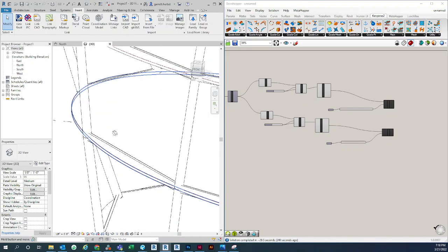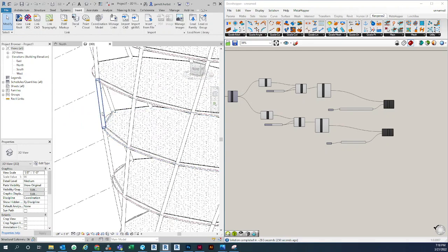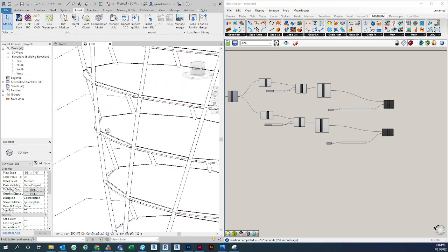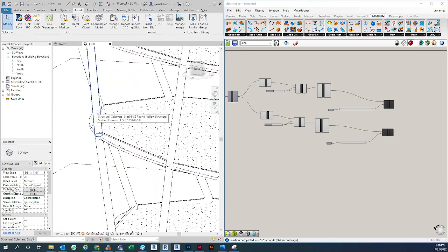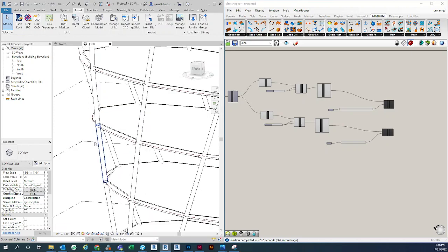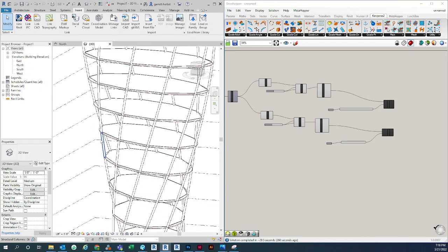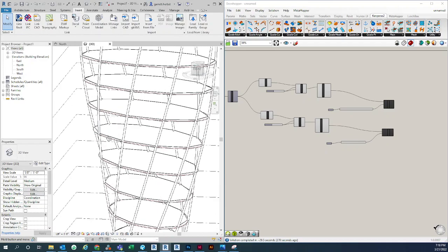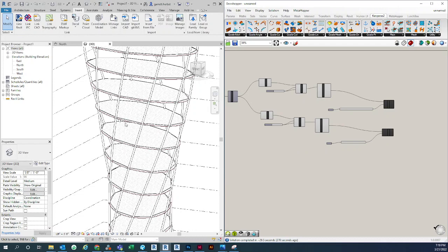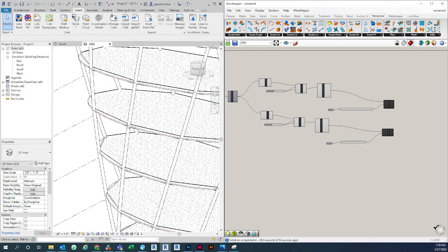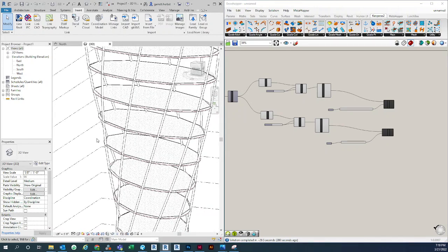What we will do is essentially offset the generating surface that is creating these columns and beams, using the dimensional qualities of the structure, essentially creating a smart script that will always offset at least the columns off of the floor slabs by its own dimension, so that they're not intersecting the slab itself.